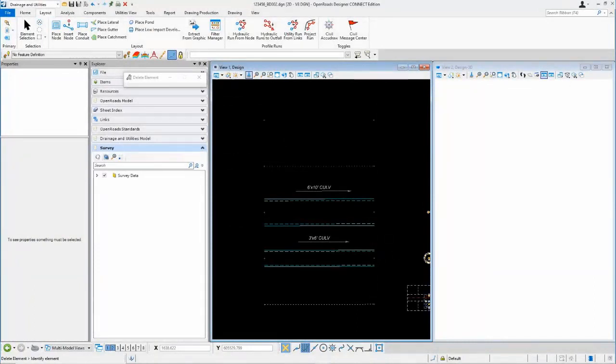Okay, the last thing we need to take a look at is our box culverts. So I had a few different box culverts that were surveyed, and there's a couple here where I just had some points and they forgot to use the begin line, end line to connect those up, so I don't have an element. And here's one where there were no attributes, so I don't have the width of that culvert drawn in. But I could use any of these points to place my box culvert, and the procedure is going to be the same pretty much for these.